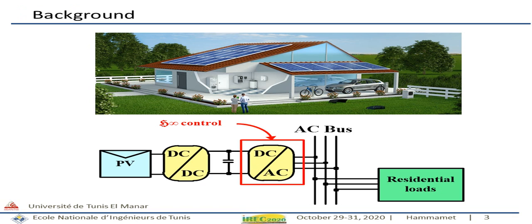Let's start with the background. Nowadays, photovoltaic systems have advanced to become one of the most trendy distributed energy systems, especially for residential applications. DC-AC converters present an essential element in this application. Proposed control strategies for these converters are very diversified in literature. However, since PV evokes specific requirements according to the singularity of residential loads and to local standards in relation with grid losses and grid impedance variation, H-infinity control presents a good candidate for this application.